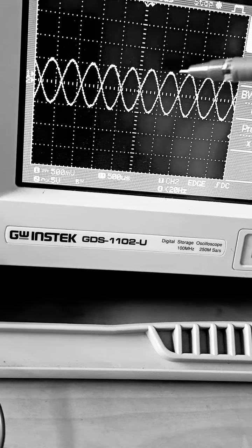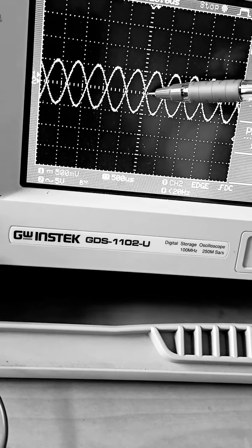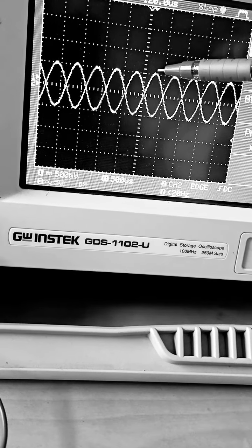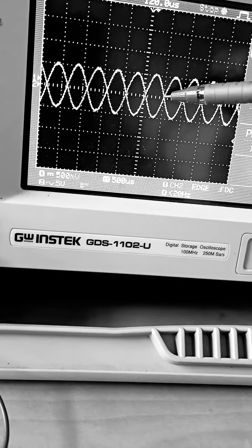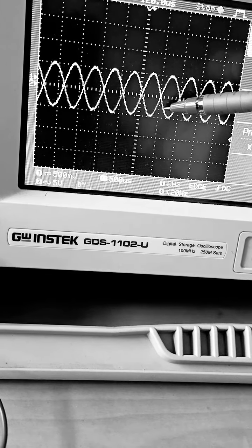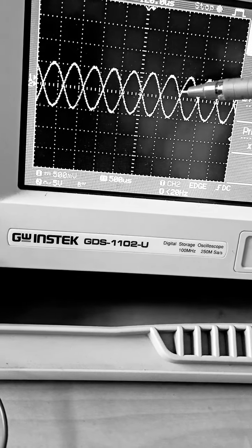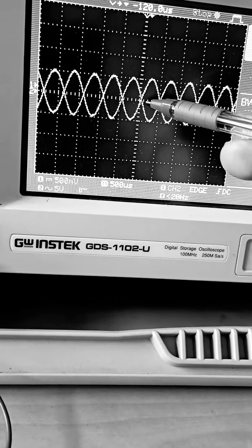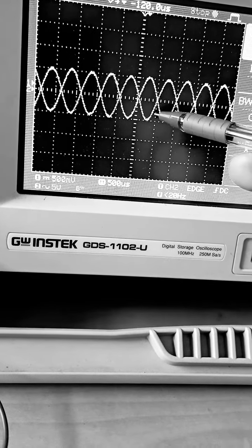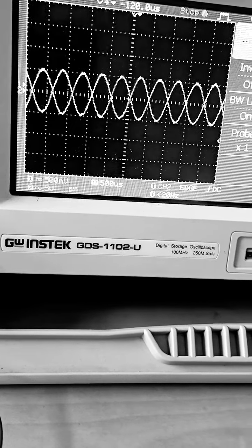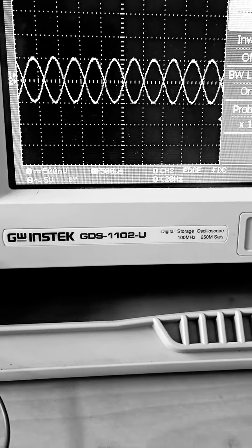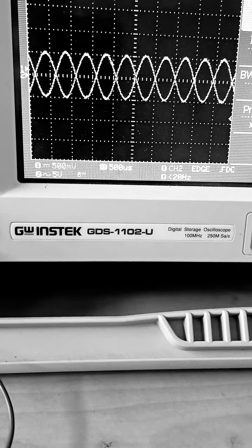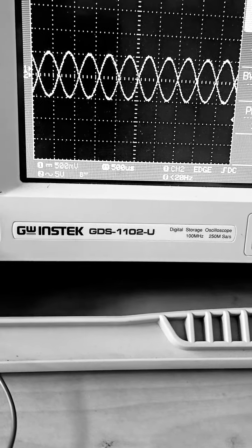if I check the yellow line, from 0 it is incrementing, reaching the maximum value, coming down at pi, then at 2 pi it is again coming to 0 degrees. But the blue line, you can see, is inverted as compared to the input. So there is a 180 degree phase shift between the input and output waveforms.